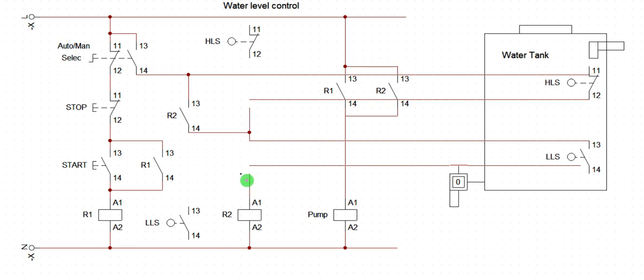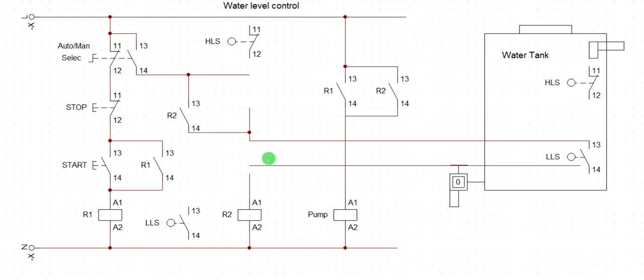So this switch here is assumed to be installed right in the tank. But you're going to reflect it here because this is a logic. This is a schematic logic. That is how we represent schematic. You are not expected to run this cable to the tank and come back. No. Schematic is all about representing logic function with symbols, using symbols to represent the operation sequence of a particular task. That is schematic. It's not a wiring diagram.